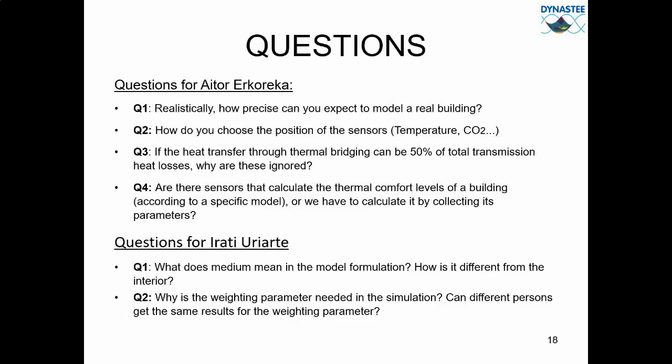And for the outdoor air temperature, outdoor CO2 concentration, and outdoor relative humidity, you have to be careful to install the sensor shielded against solar radiation and in a place that usually is the roof, if it's possible. That's usually the best place to get this type of measurement in the exterior of the building.